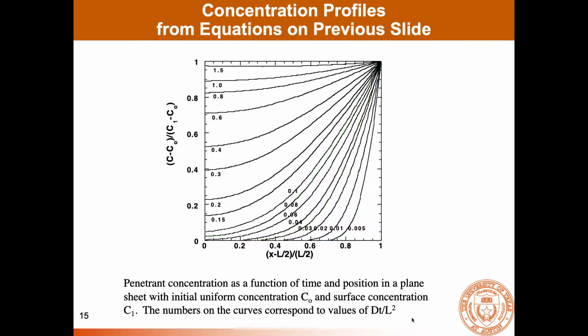Now, as the concentration profiles from the two sides meet, and you start to have a concentration at the center of this film, then the net driving force for transport, that is the difference between the concentration here and the concentration at the lowest value in the film, starts to decrease. It goes from a maximum value at the beginning of the experiment and then gradually decreases.